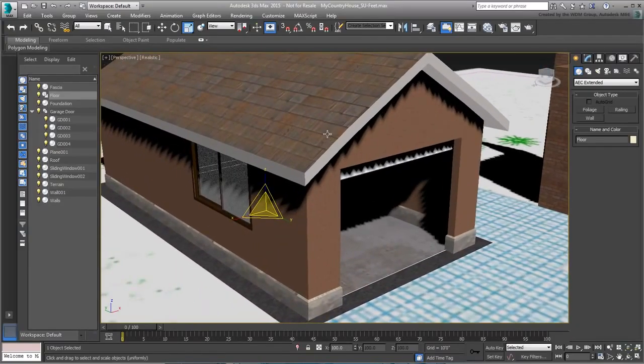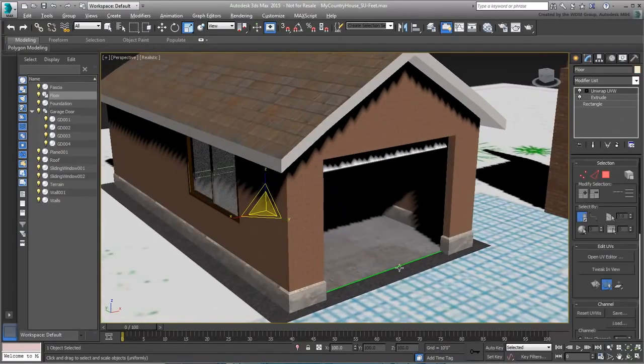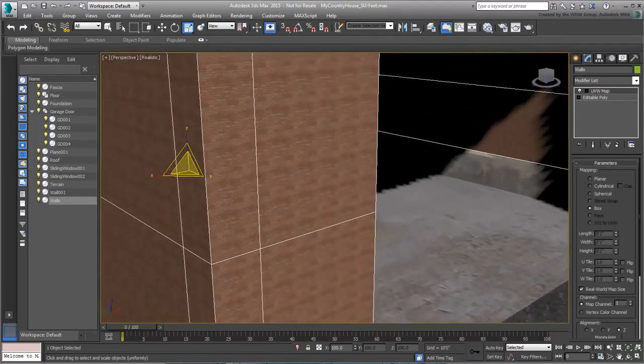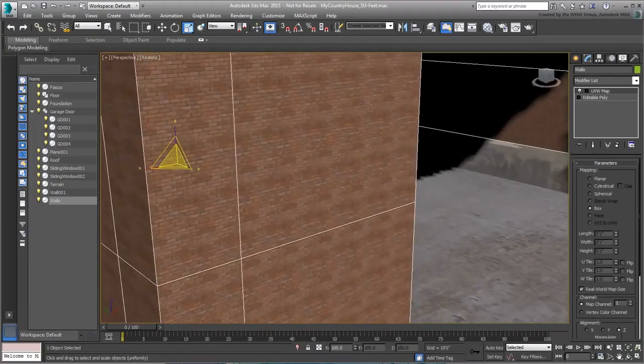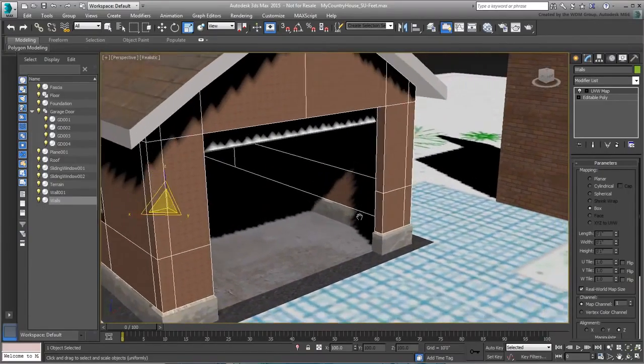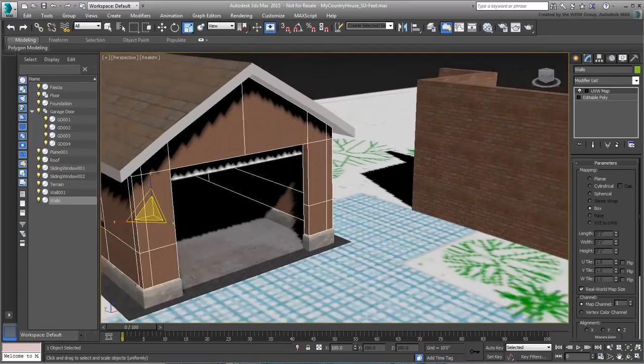Any mapping coordinates that are using a gizmo of some sort to define projections are working flawlessly. The roof, foundations, and cement floor do not need any interventions. The walls, though, certainly have a problem. The bricks on the walls are way too small now. In fact, 12 times too small as we move from an inch base unit to a foot base unit. There are 12 inches to a foot.